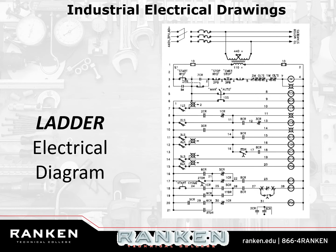It's that simple. And I never understood it, right? It took me like 4 years of beating my head against a wall trying to troubleshoot ladder diagrams before it finally made sense, right? I was always worried about what kind of switch it was. Is it a pressure switch? Is it a float switch? What kind of switch is it? Doesn't matter, right? It doesn't matter if it's a contact. It doesn't matter if it's a limit switch. It doesn't matter if it's a selector switch or push button. What do they all have in common? They got to close. Make it close. It doesn't matter what causes it to close. It just needs to close. Once it closes, Pooh Bear gets his honey.